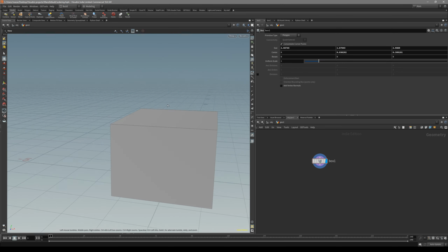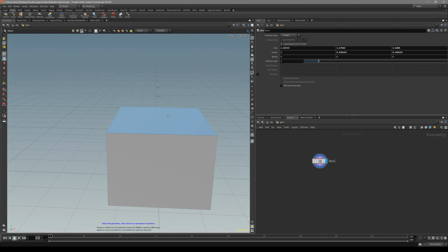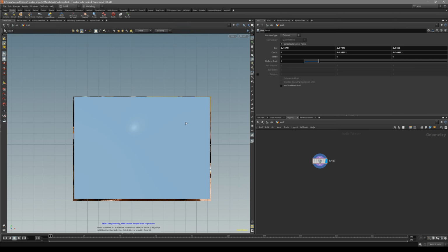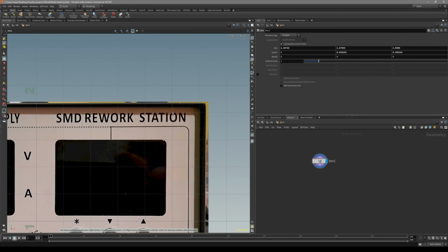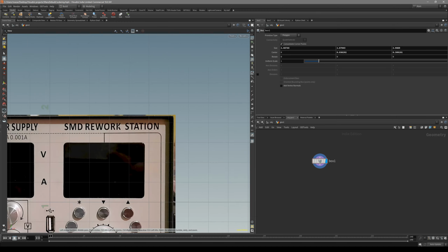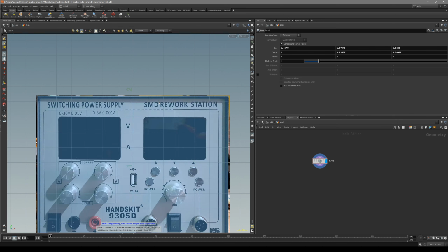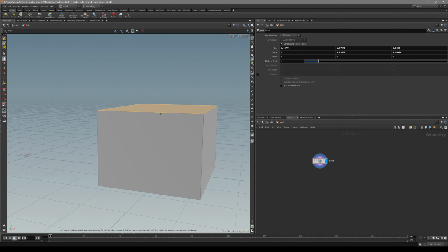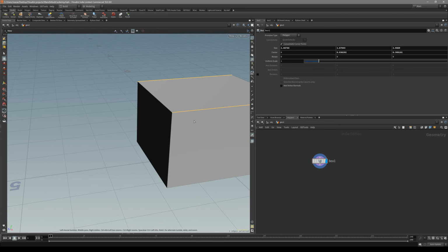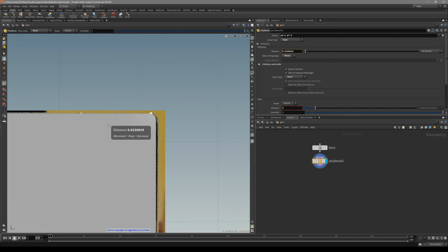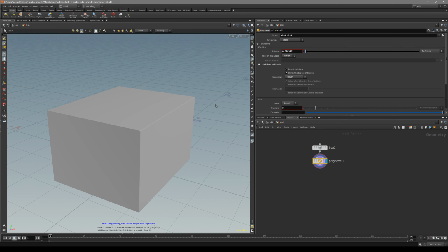Now that we have taken our detour with the extraction options and how we can duplicate our polygons, let's start with actually doing some modeling, and let's actually extract this face for our modeling. But before that, let's take a look at our model. We know that we have this kind of a beveling around these corners. So before we extrude any of these faces, we want this extrude to follow these faces. So what I'm going to do is actually select these top faces and start beveling it. So it doesn't have to be a very subtle bevel, but it still has to be here. Maybe something like this.